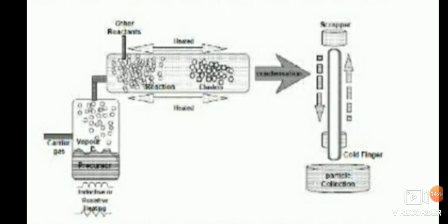In the simplest form, a metal organic precursor is introduced into a hot zone of the reactor using a mass flow controller. Besides the increased quantities in this continuous process compared to GPC, that is gas phase condensation, it has been demonstrated that a wider range of ceramics, including nitrides and carbides, can be synthesized.